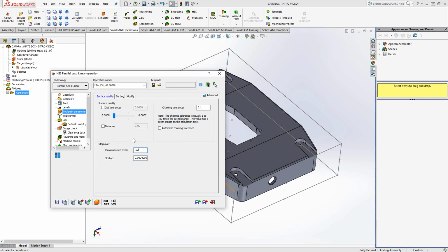If you work with translations of STEP files, IGES files, Parasolids, and there's something wrong with the surface, it will affect your toolpath. If the surface was translated with an erratic nature to it, and you want to reduce the tolerances of that surface, you have the slider, or you can put in a value here. All this is really just to control the quality of that surface, how closely you follow that surface.